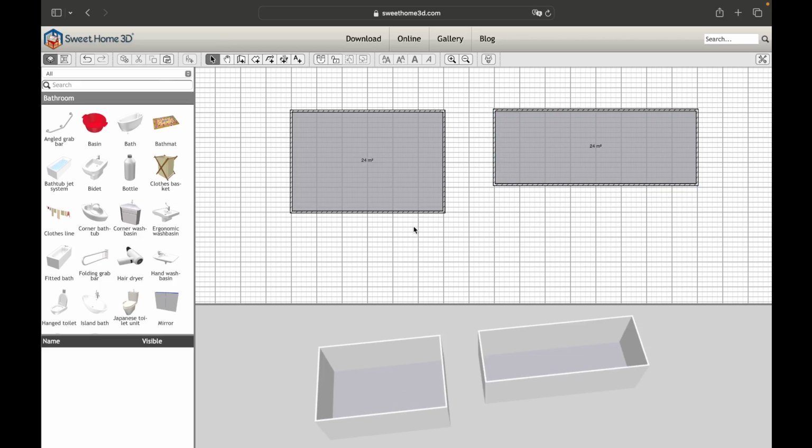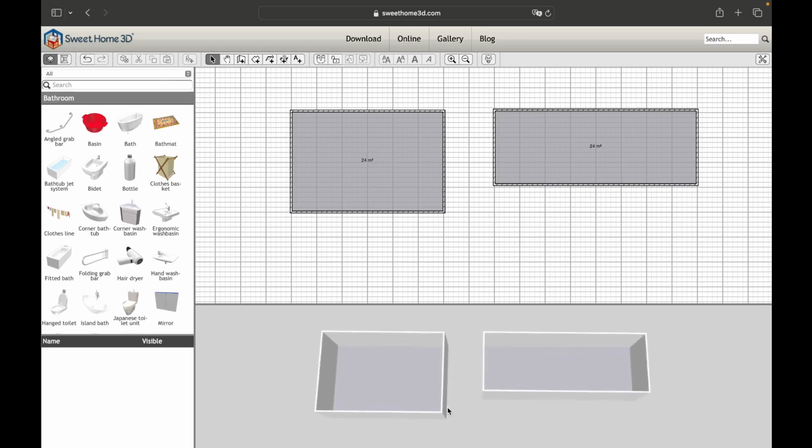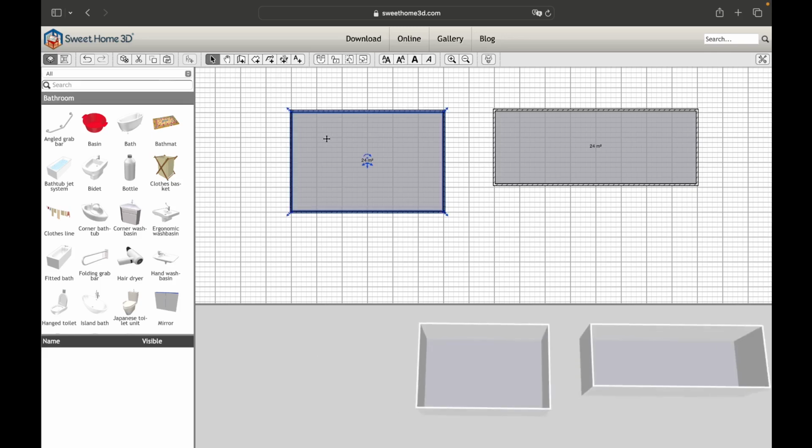Dimensions are of great importance when submitting your project for construction. Inside our workspace, there is already information regarding the dimensions. The square footage indicated within the rooms can be translated and rotated as previously mentioned by selecting the Select Objects command, clicking on the surface and using the available icons. We can change the size of the text by clicking on the Increase and Decrease Text Size commands and change the style by activating the bold, italic, or both commands.